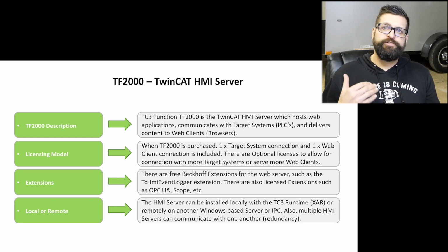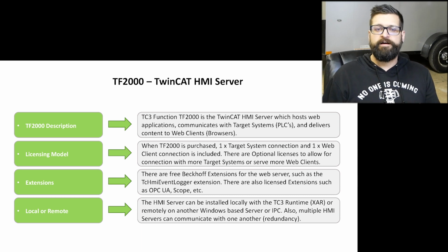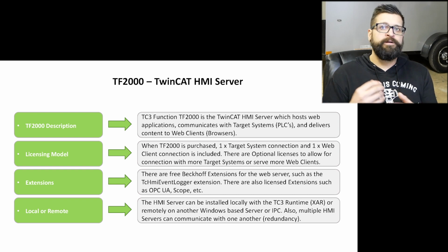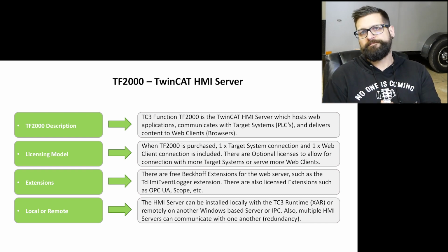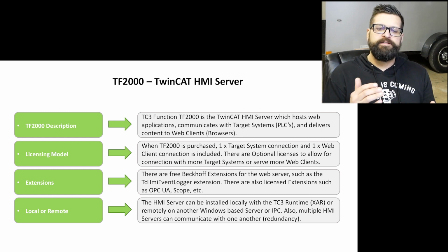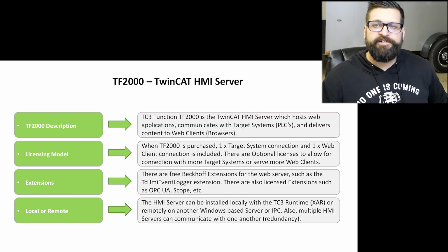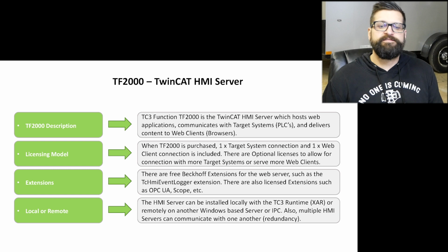That connects you to a target system's event log, so you can pull off alarms and errors, either user generated or system generated. So the terrible things like page faults that were probably going to crash your system, anything like that will be fed back to the HMI, and it can be natively displayed and filtered in the event grid control that Beckhoff provides.